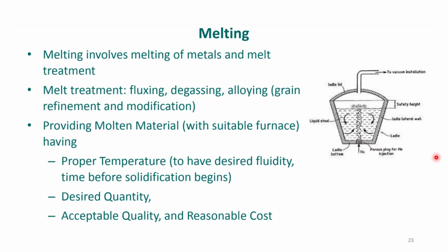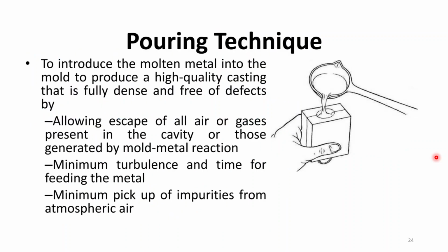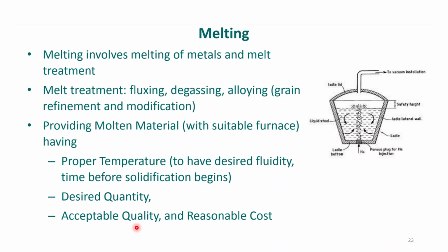The higher the temperature you have above melting temperature, the higher the fluidity and lower the viscosity, and the longer the time before solidification begins. Next is desired quantity. So for the furnace also, you select it in a manner that you can have the desired quantity as well, acceptable quality and reasonable cost.